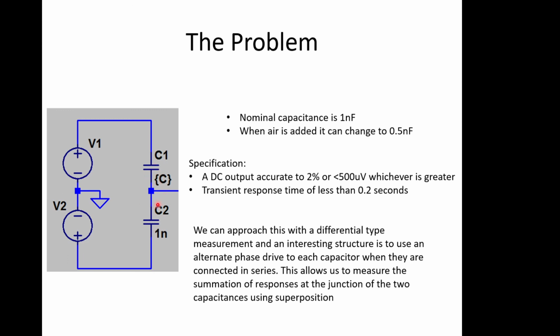So again, it's a differential signal. Any change in temperature affects these equally, becomes a common mode signal. And we need to drive both ends of this system. Because of the nature of dielectrics and the value of dielectric of air and the typical value of dielectric of fuel, normally when it's full of fuel you'll get 1 nanofarad for the size of the plates that we've used, and when it's just full of air this will change to half a nanofarad.